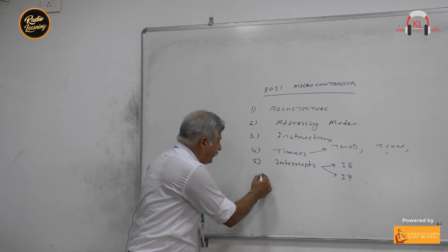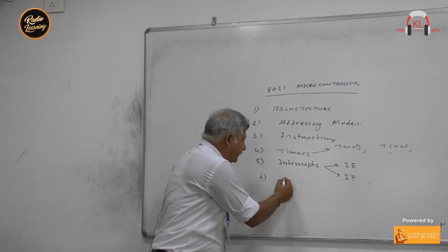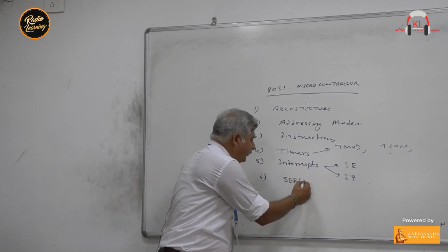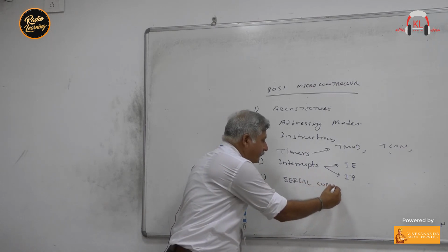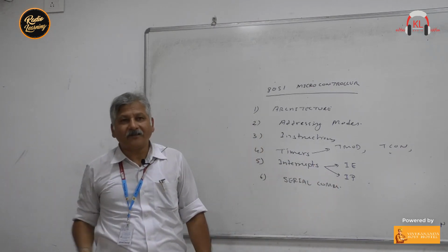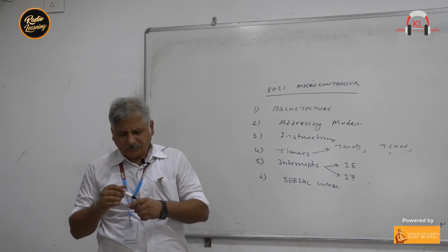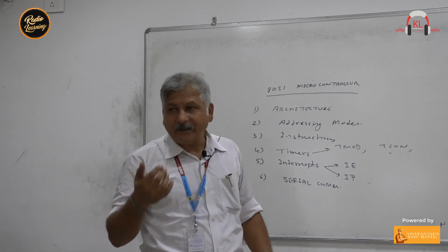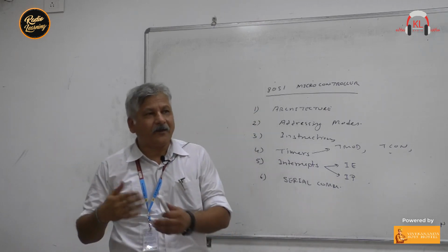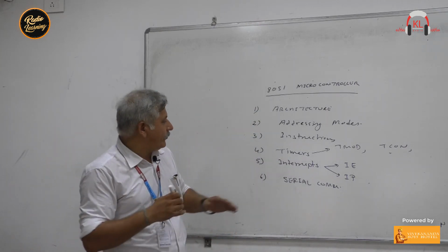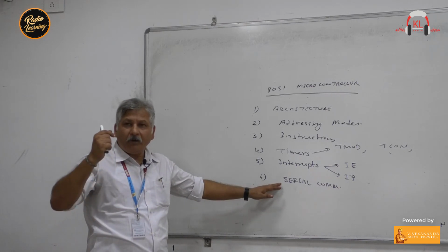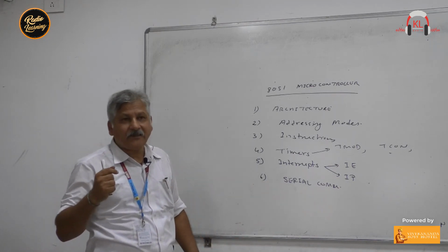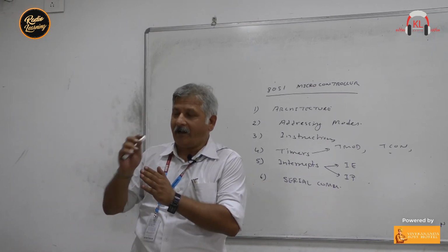Then you should study serial communication, how to transfer data serially. When we are transmitting or receiving data serially, at that time we have to transmit or receive the data with a particular baud rate. For example, 9600 baud, you have to transmit the data.